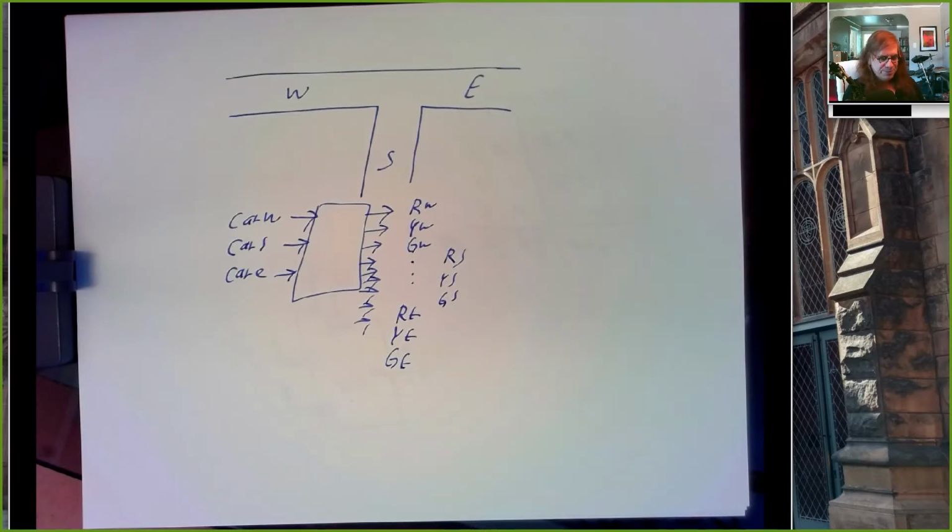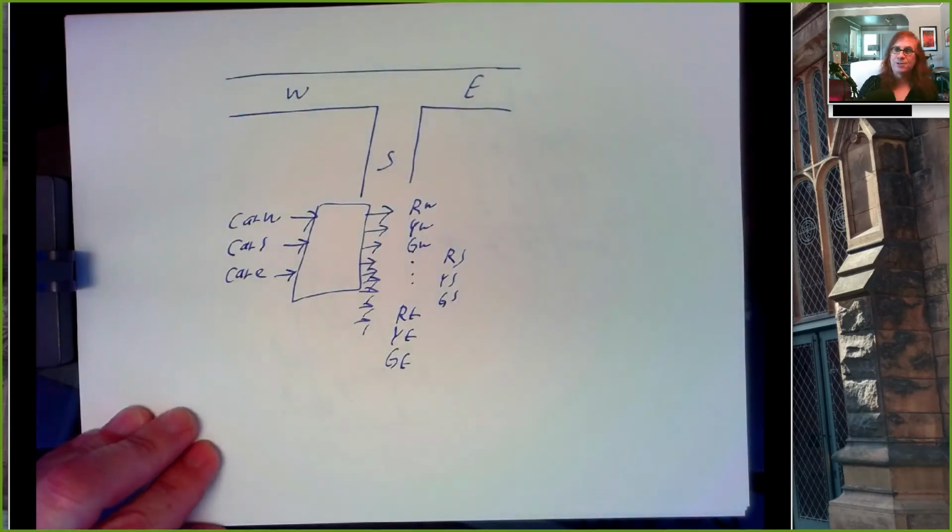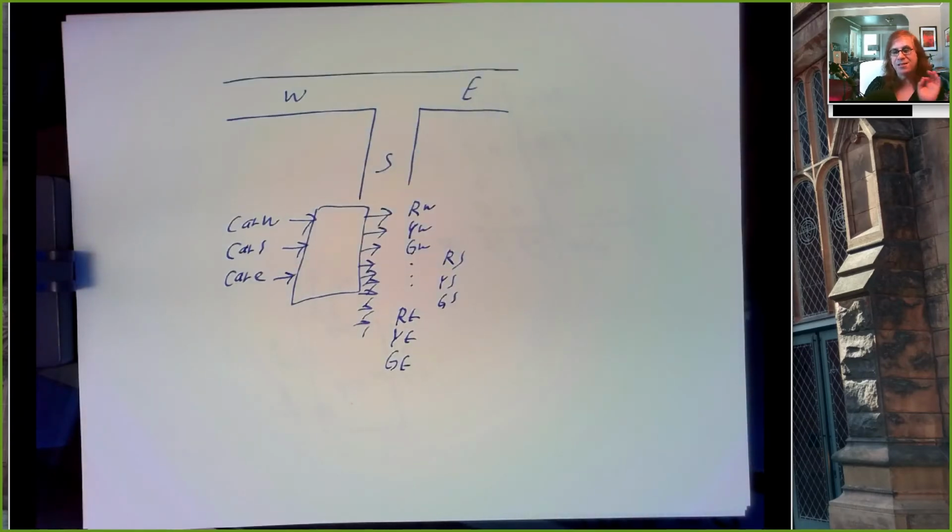And I don't recommend trying to do what you did in Lab 6. In Lab 6, using the old green and the delayed old green was simpler than thinking of this as a general state machine. That was a trick that we used, which said if we just use a delay circuit, we can look at the old green and the delayed old green and figure out what color a light should be. But we can do something a lot easier if we're working directly in Verilog, which is to actually think of this as a state machine.